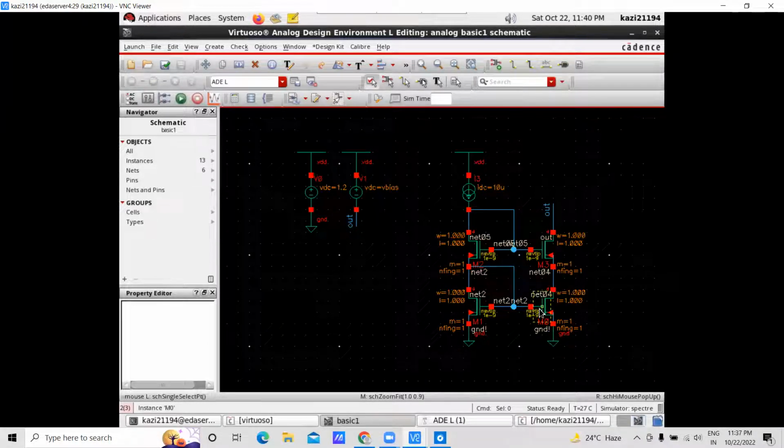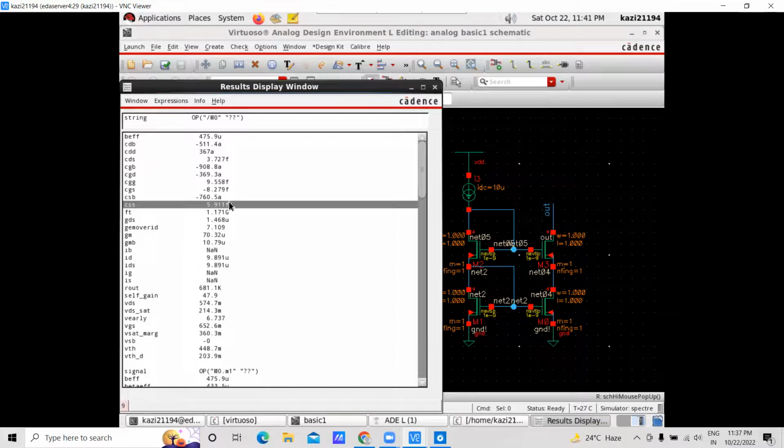For example, if you want the parameter value, let's say I don't have any parameter value for an NMOS. I want the lambda, I want the mu and cox, and let's say I want parameters on similar lines. So what I could do is just run a DC simulation, click on it, and get the lambda value. So yeah, the lambda value is not there, but early voltage is there. So early voltage reciprocal of that gives the lambda. So yeah, early. Let's press E.